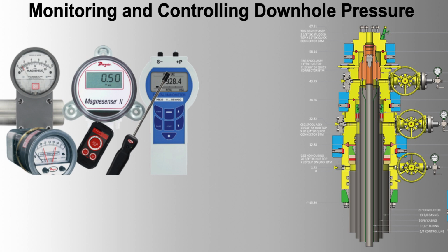Example issue 5. Overpressure events during production. Problem. Overpressure events leading to equipment damage and safety risks. Solution. Implement automated control systems that can quickly adjust choke valves or alter flow rates to maintain safe pressure levels. Use predictive analytics to anticipate pressure surges and take preemptive actions.